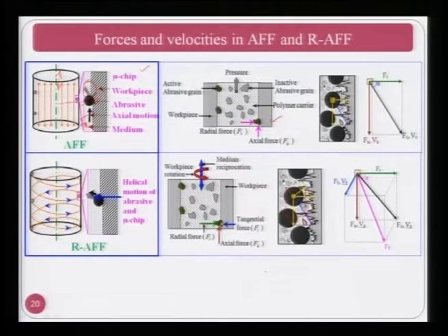Now, how it is shearing the peaks is shown in the last figure, and you can see smaller pieces removed in the form of microchips by the abrasive particles. The last figure on the right hand side shows the radial force acting on the abrasive particle and the axial force acting on the same abrasive particle, and here is the cutting force, or resultant force, Fc.